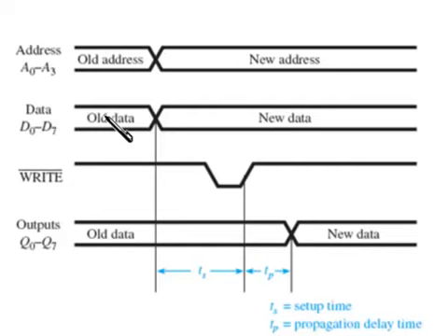And same with the data. So with the address bus, here's the old address information. Here's the old data information. And like I said, you change the address to the new address you want to write to. You change the data for the new data that you want to write to that address. And then after a length of time called TS, which is the setup time, you drop the write line low, and when it goes low to high, that low to high transition has to occur TS nanoseconds after your address and data is present. That's called the setup time. So in other words, make sure the address and data is there before you make the write pulse occur.